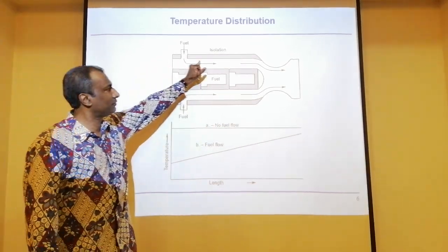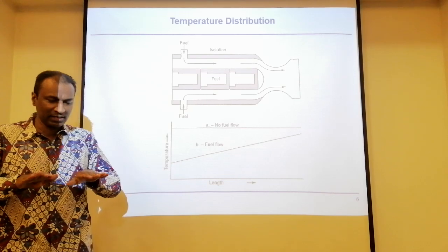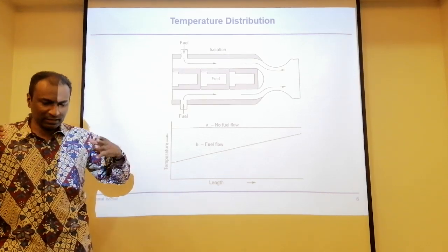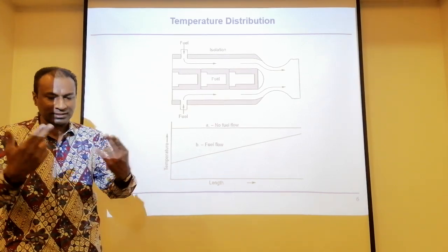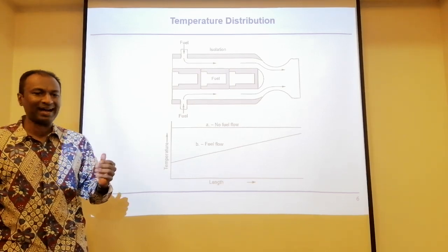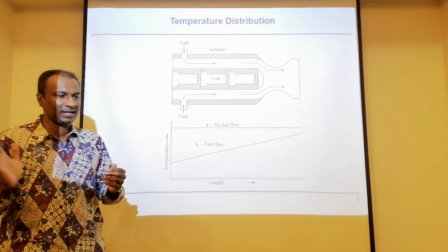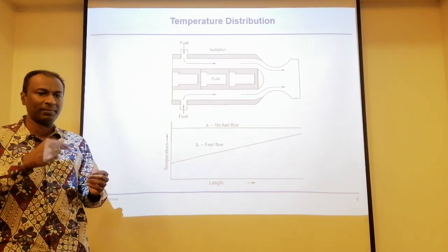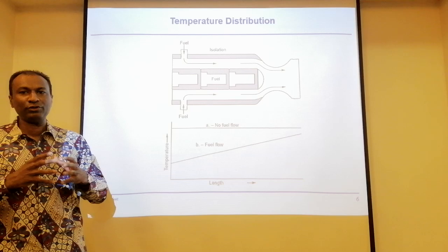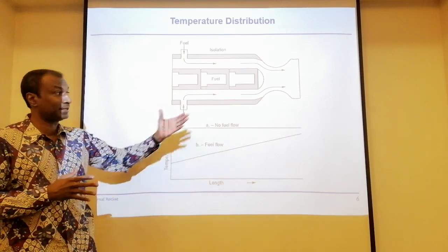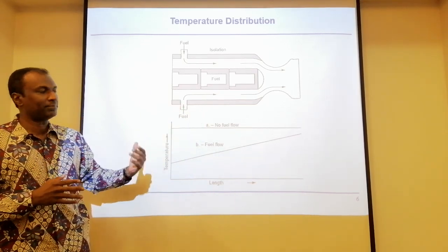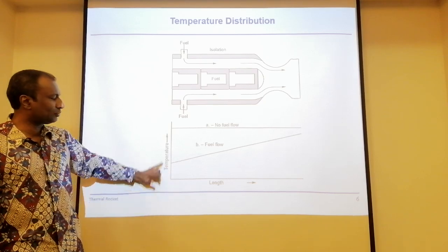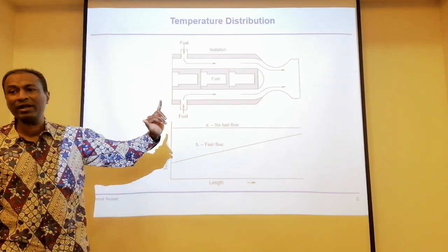If you look at it, the fuel will run through the skin. There is actually piping which goes over the nozzles in order to harvest the heat. When the heat is harvested, that heated fuel will be injected into the chamber, and burning takes place. So you are optimizing the heat and the burning as well. It also helps to cool down the nozzles.